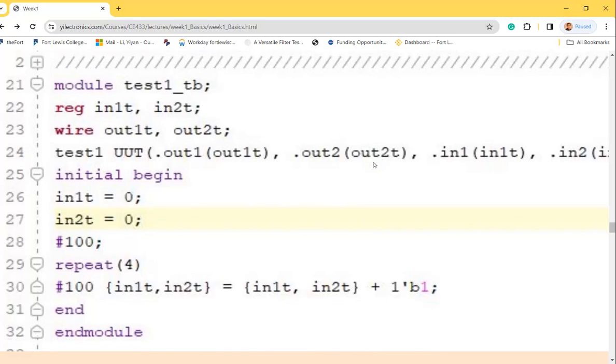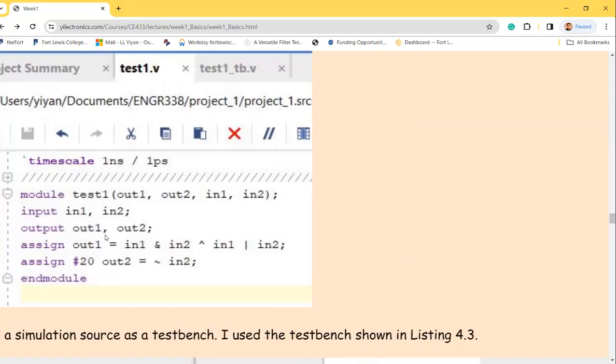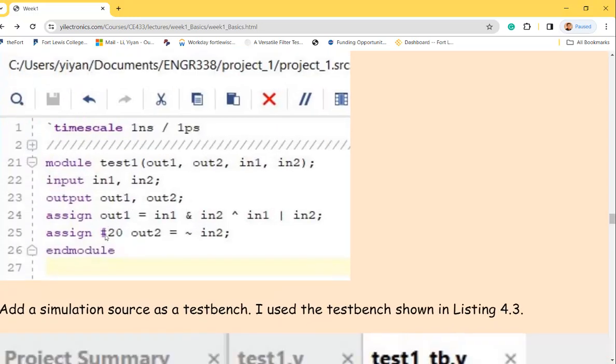Since the assignments aren't happening sequentially, we have to include the time of the first assignment as well. The time of the first assignment, which one? This one? Back up on the last picture you were on, because we're not assigning them sequentially, right? So wouldn't however long assigning out 1 takes be added on to the 20 nanosecond delay as well? For L1 or L2? Out 2. Because it'll assign out 1 before starting the 20 nanosecond delay, won't it? Yeah. So it'll take like an extra nanosecond to assign out 1, and then we have 20 nanosecond delay in